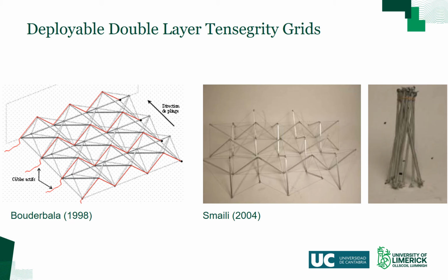These types of structures can typically be easily stored, transported and erected within a short time frame, allowing for many uses such as temporary shelters, exhibition roof structures, etc. A potential advantage of Tensegrity structures is their kinematic indeterminacy. When arranged as a foldable system, only a small quantity of energy is needed to change their configuration because the shape changes with the equilibrium of the structure. As a result, these grids are potentially optimal structures to be incorporated into space applications or temporary shelter structures.